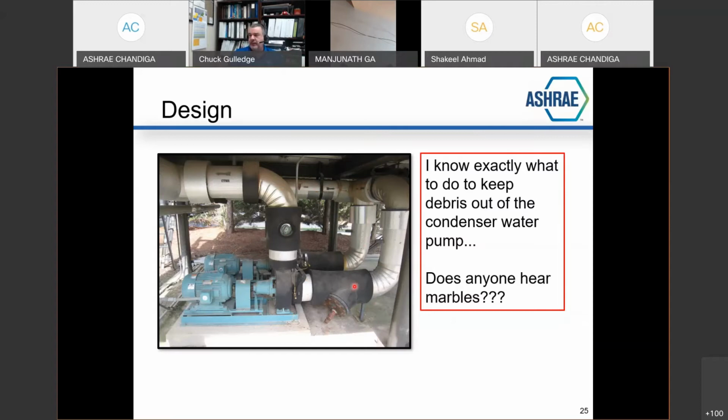So when we're picking condenser water pumps, we're always having to pay attention to net positive suction head. We get a little bit of free energy, so to speak, just by atmospheric pressure. And then we get this little vertical head here that helps push the pump. And these pumps were actually picked to be at a safe point with their net positive suction head based on this geometry of that head and the atmospheric pressure on the water inside the basin.